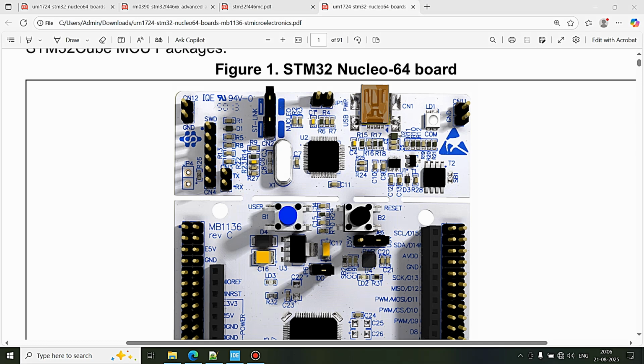Hello everyone, in this video we are just going to develop the UART peripheral drivers, which is also required for the RTOS development process. Let's get started. In the previous video we developed the bare metal driver for driving an LED connected to PA5 of the same Nucleo development board, and in this video we are going to develop the UART serial communication TX process, which will be most likely helpful for our RTOS development process, that is, real-time operating system development process.